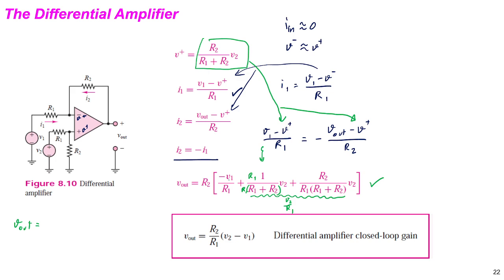And then V out will be V2 R2 minus V1 by R1 plus V2 by R1. Okay, and we can get this final formula. So this type of circuit will subtract the inputs, V2 minus V1, and this is the gain. Again, we call it a differential amplifier. How different are our signals? We get the output of how different our two input signals are.